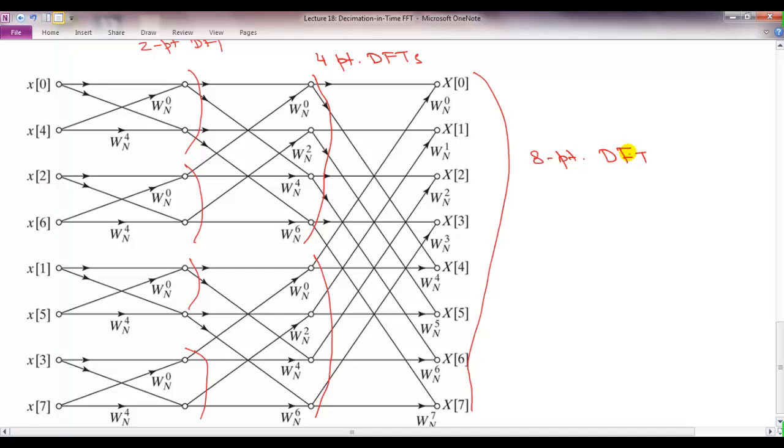Okay. So computing the DFT can be simply done using this recursive expression. You start with a sequence, keep on dividing it up to 2. The only real thing you compute is this 2-point DFT. Then you go back, you do some more multiplications, compute the 4-point, 8-point, 16-point, 32-point, and you keep on going, whatever was the length of the sequence. If you had a bigger sequence, if you had, for example, a 16-point DFT, you would have done the same thing again after this. You would have one block which looks like this, another block which replicates this. You multiply them in the right way to get a 16-point DFT.